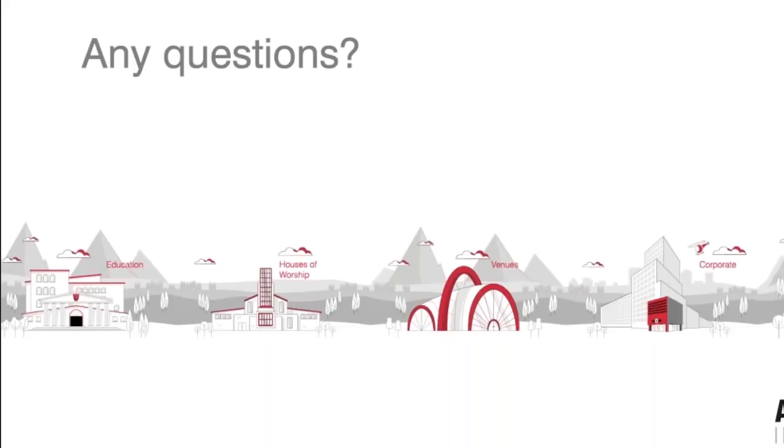I may have done okay. And within a couple of days, we had, I don't know, 5, 6 more examples ready to go. The reality is that to control something, once you get familiar the first time with the editor, that's very, very quick indeed. So you just drag in a control object, assign it to channel 1 level, upload it to the mix rack, and in a matter of minutes, you have it running.